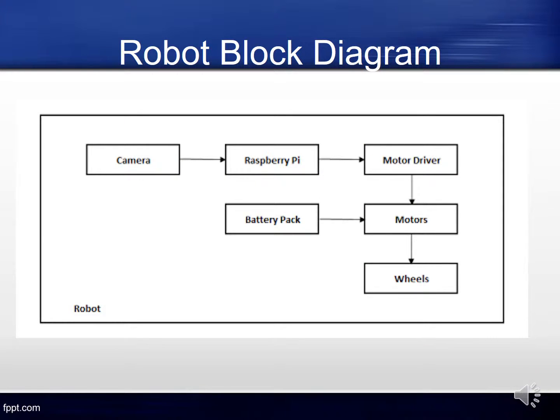Dear Dr. Sudeep, this is Vasant Ramaswamy and I'm going to explain the software part of the project. I'm going to start by explaining the block diagram of the robot. We have a Raspberry Pi camera mounted on the robot chassis. It communicates using the camera serial interface with the Model B plus Raspberry Pi module. The Model B plus computes the Hough transform and the Canny edge detection. The basic idea in this project is to find the center of the object and align it with the center of the image.